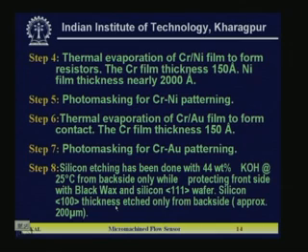What are you doing here? If you need a long time etching, since the chromium gold or chromium nickel has already been patterned on the top, the KOH solution may damage the gold or chromium nickel film. To prevent this damage, normally the top side is covered with a protective layer, and in many cases we use black wax. On top of the black wax you can press a 111 orientation silicon wafer, which normally does not etch by KOH. So the top side will be protected, and from the back side you can pattern, so that you can get a cantilever or membrane.